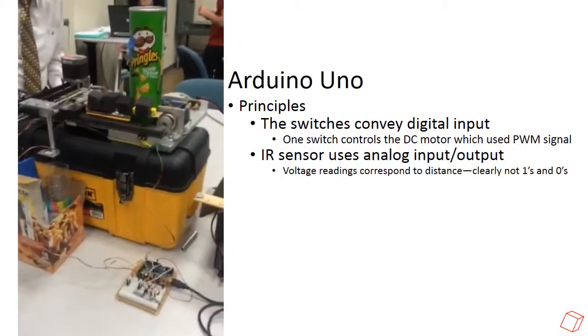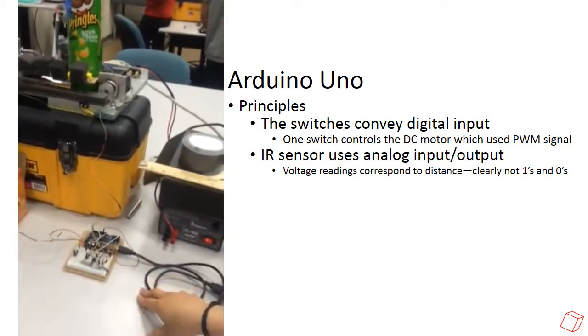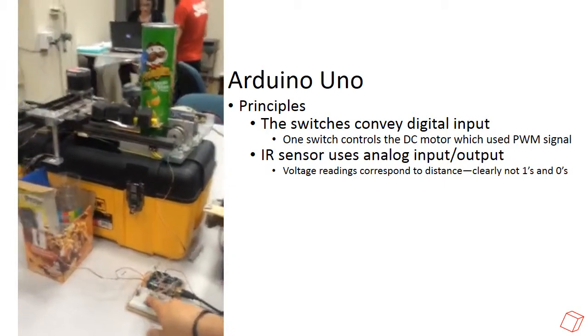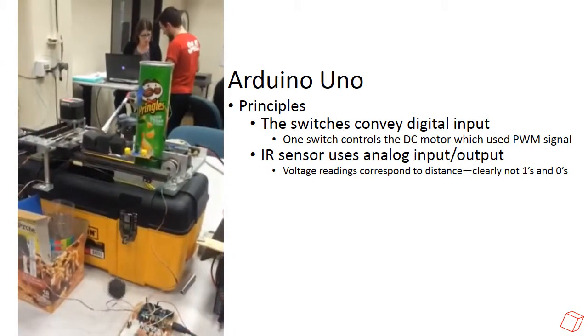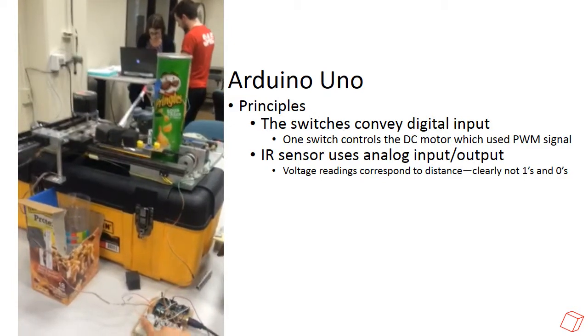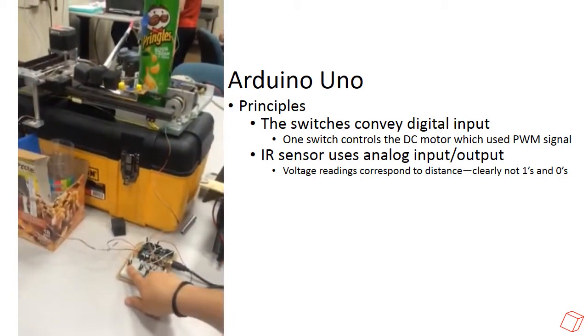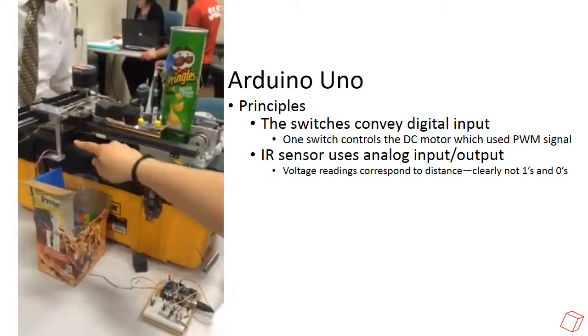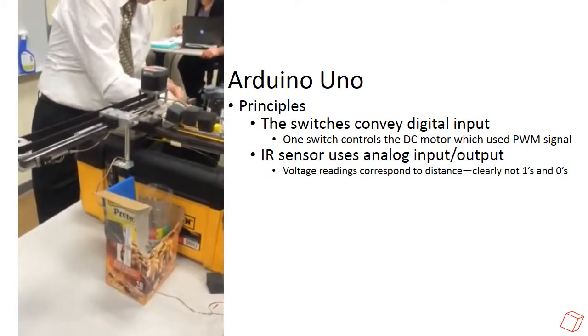The program controlling this Arduino uses a while loop to keep the motor responsive at the touch of a button. The while loop is terminated when the second switch is pressed. Once the while loop ends, the program communicates with the IR sensor and a new distance is saved.